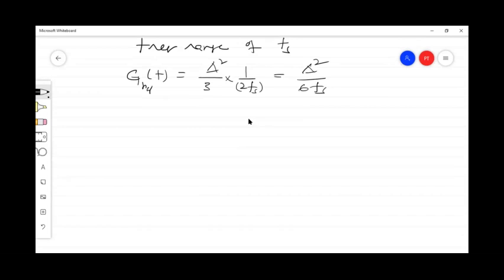Okay. So this is the quantization noise power spectral density as far as a DM system is concerned. Now we need to find its corresponding noise power, the quantization noise power PNQ, obtained by integrating over the band of the message signal. Let us say the message signal frequency range is from 0 to fx, where fx is the maximum frequency, or W. If you are talking about a two-sided spectrum, you can take it as minus fx to plus fx.